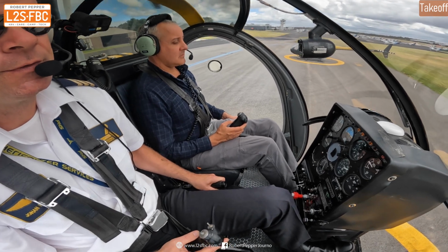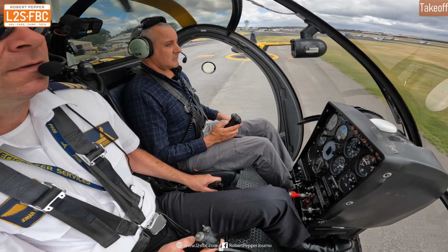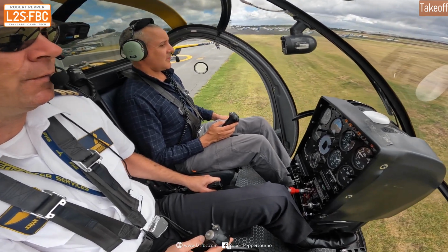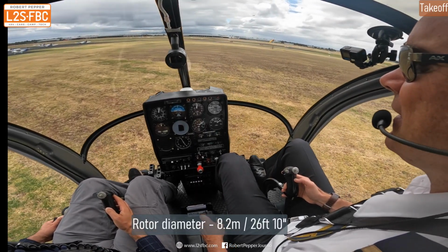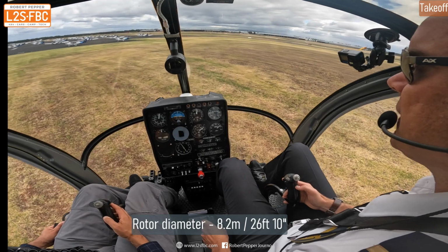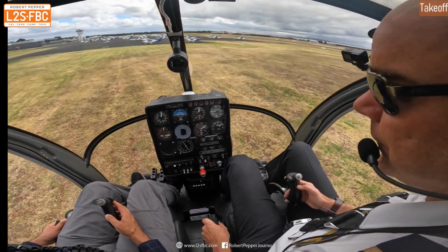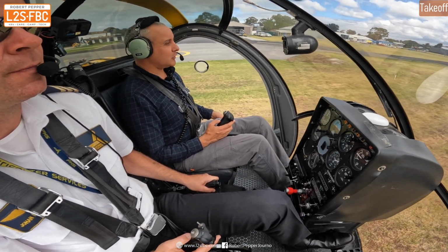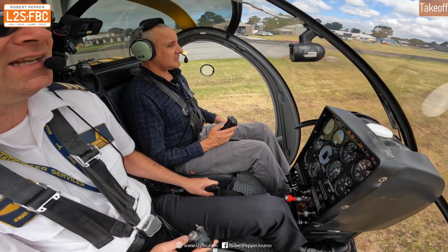So we're hovering at the moment, and we're going to move forwards, but look that the cyclic isn't really moving. There's almost no difference between the movement required to get the aircraft moving forwards and the hover. It's almost like you just don't make one of the corrections. And again, moving to the left, we're actually probably yawing the aircraft as opposed to banking it, because at low speed it's more kind of a yawing movement as opposed to banking. And we're back into a hover again, and again no massive movements of the controls to bring it to a halt.